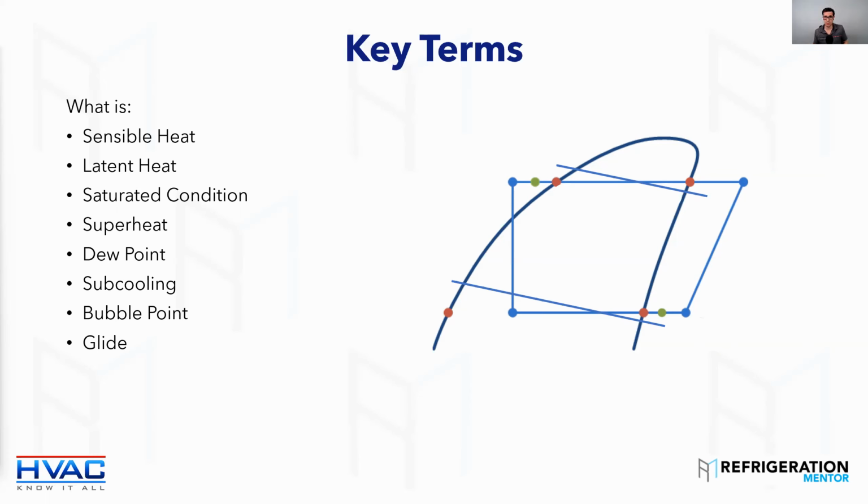And when I talk about the average point, how you get it is you take your bubble point temperature and your dew point temperature, add them together and divide by 2, and that gives you your average or midpoint. A lot of apps give it to you automatically. But when you're setting up certain valves and systems, you need to start with that midpoint. For example, an EPR in refrigeration is an evaporator pressure regulator. It holds an evaporator at constant pressure, but you would start at the midpoint, and then you adjust it to temperature. Everything I do now when I'm working on refrigeration, I adjust in temperatures.